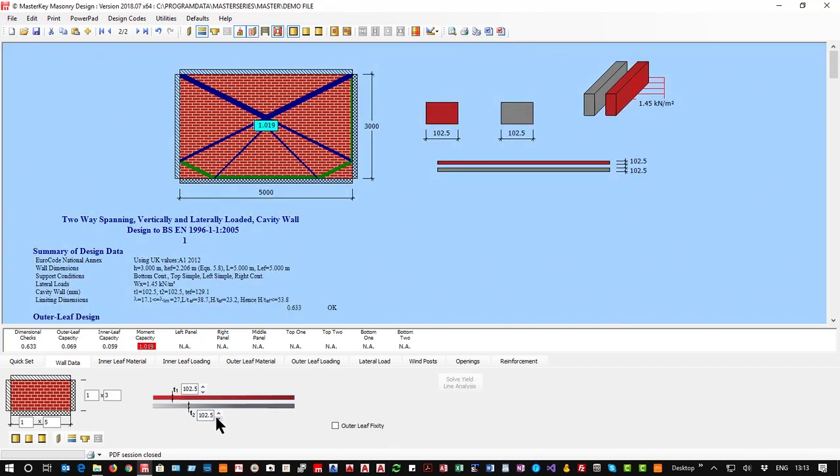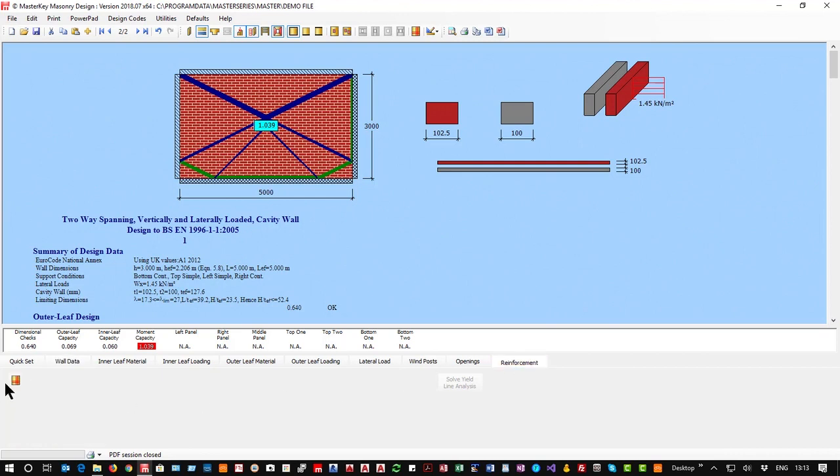If I wanted to come back and stay there, didn't want to reinforce or make the other side continuous, my next option is to put on some bed reinforcement. So we're stepping through the ways of making our wall stronger.